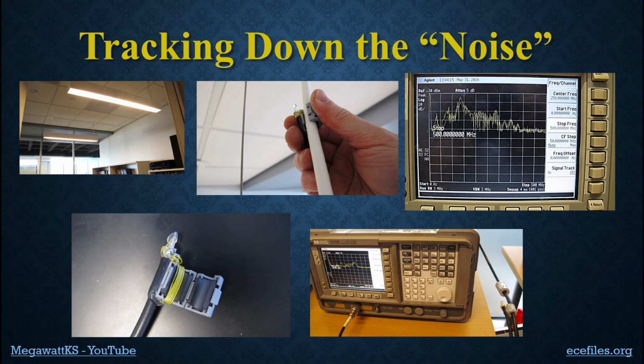Okay, I blamed the RFI primarily on the lights in the ceiling in this building, and that was for 2 reasons. One is, in other videos I can show, when you turn the lights off in the room, the RFI noise that you get out of the radio is significantly reduced, but not enough to really receive very many stations, maybe one more station. So it's still very strong even with the lights off in that particular room. And why is that? Well, the hall lighting is still there for safety purposes, and there are other people in the building. And remember, the wires that go to these lights travel throughout the building and the walls, so they're just radiating everywhere.